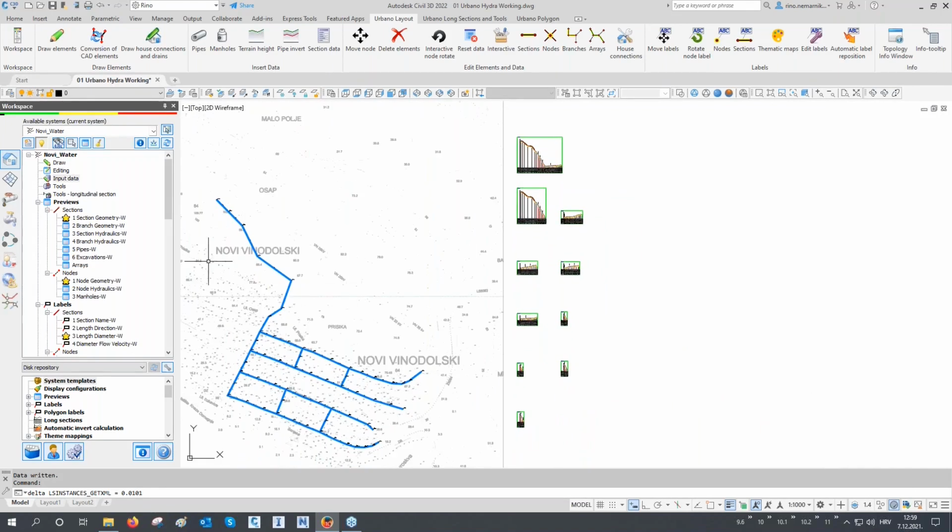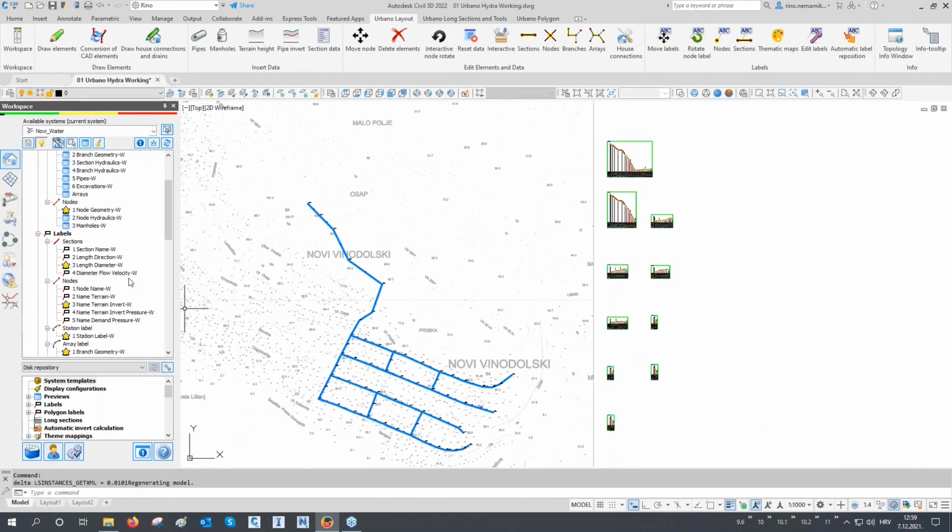So to draw cross sections, it's really easy, just like how we draw the profiles. You have different configurations. Inside of the configurations, you can save everything from colors to data to hatches to dimensions, everything. So let's just open the one that we will use. I will use this one in a higher scale, so 1 to 50. The cross sections will be bigger than the plan itself.